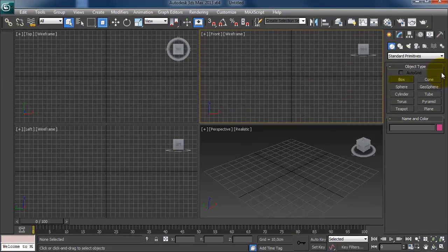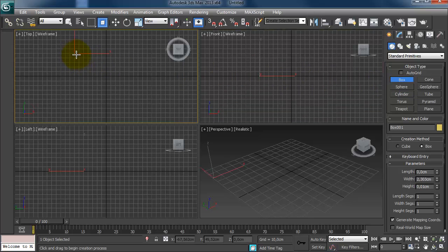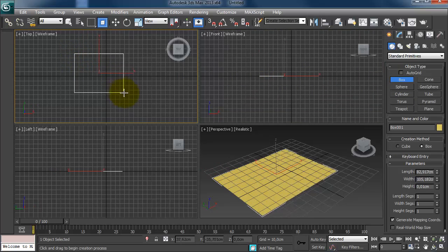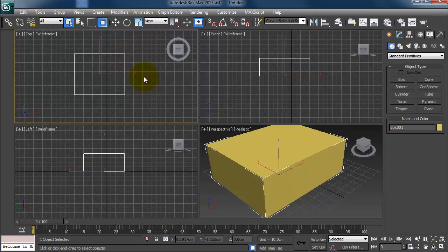The first object we're going to create is a rectangular prism. By clicking on the Box button, highlighted, and in the first viewport at the top right, click with the left button of your mouse, dragging it towards the bottom right to draw the base of the box onto the plane. Once you've reached the desired size, release the left mouse button. Now drag the mouse upwards and you'll see that the box acquires volume. Click again with the left mouse once you've reached the desired height. Finally, right-click with the mouse to finish off.